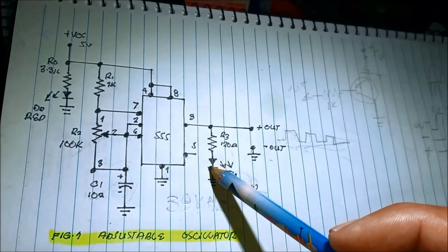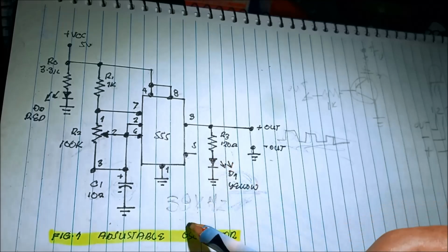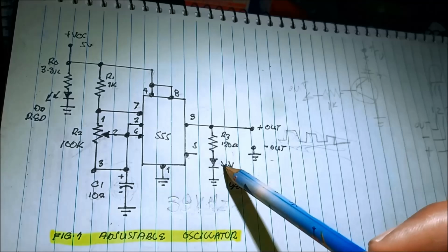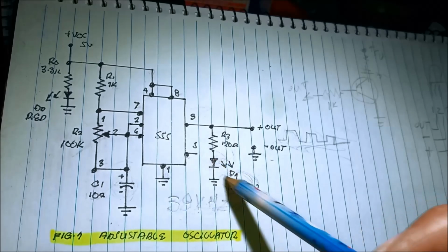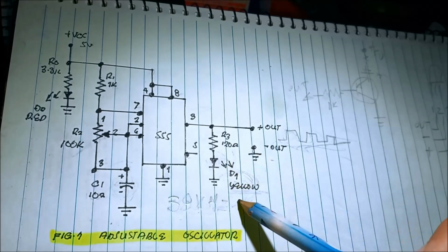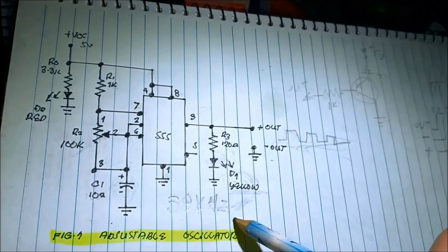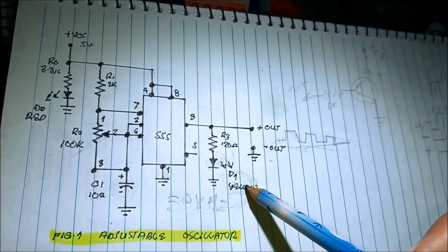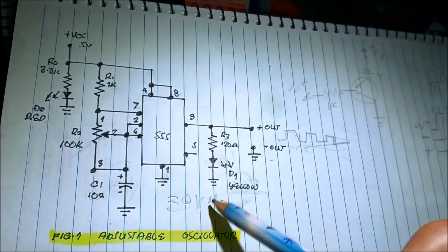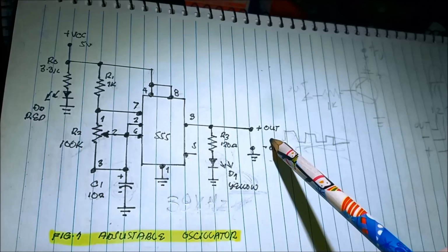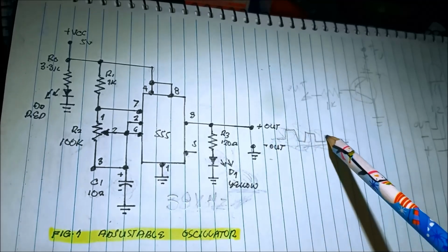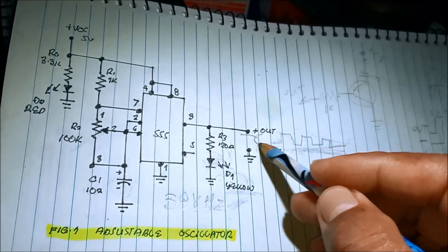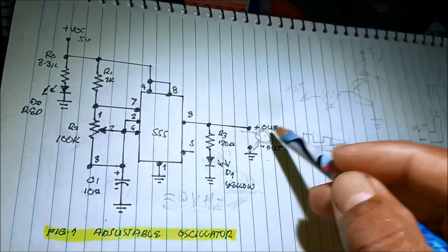It is almost impossible to see the blinking because the frequency is 38 kilohertz. So we can see the output LED yellow as if it is a steady light. We just turn on the LED, but its frequency is 38 kilohertz, and the square wave is generated into the output by connecting the oscilloscope to the output.